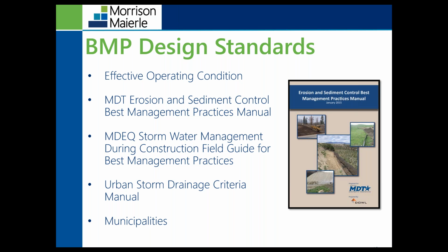I personally like to use the MDT manual. The reason I use it is that it has pictures of the BMPs, has definitions and purposes of the BMPs, the objective, the effectiveness of the BMP, any alternatives of the BMP that you're trying to choose. BMPs you can use in conjunction with, the limitations, materials, design, installation, the inspection and maintenance procedures for the BMP, removal, and also has details for the BMP. These BMPs must be kept on site.